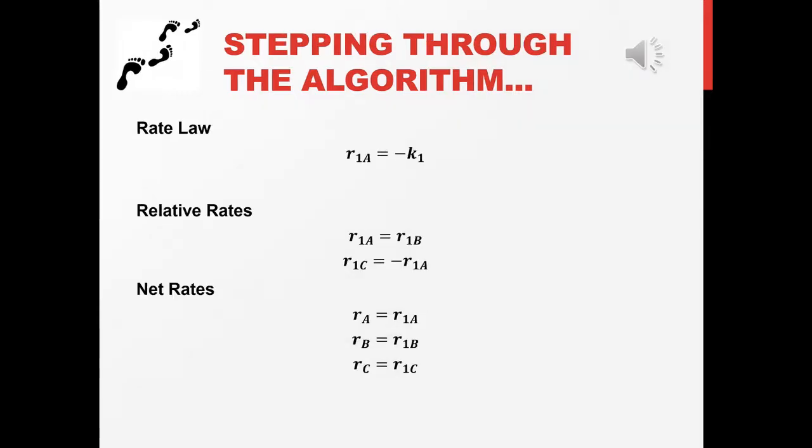The next step was to define each rate law. The literature for our process confirmed that the rate was zeroth order. Therefore, the rate of reaction is simply dependent on the reaction rate constant, k. As mentioned previously, the high selectivity of our desired reaction allowed us to neglect the impact of the undesired reaction.